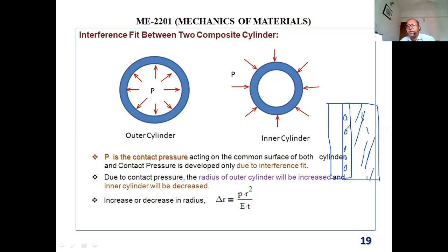So these rivets, you need to take them out. All the rivets are made of very soft material. They have a machine to take them out, and then you put in a new plate and try to join it there. Say the initial rivet size, just for example, is 0.575 inch diameter. The hole diameter is this much.